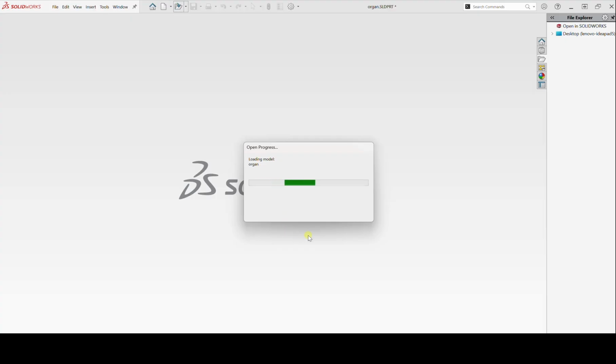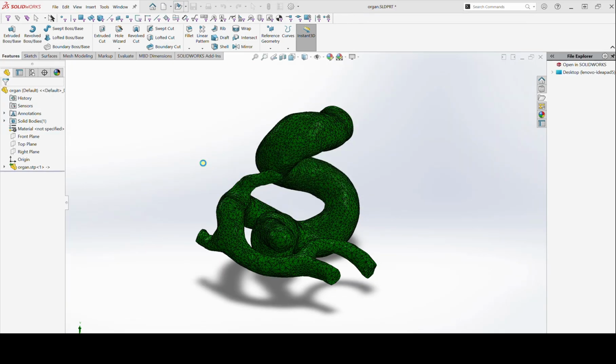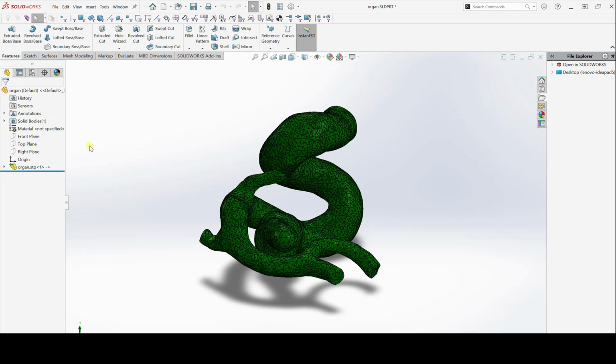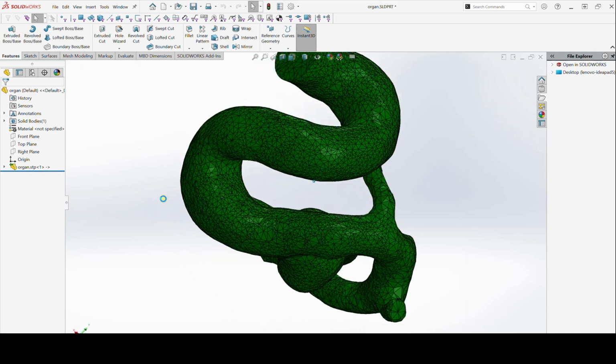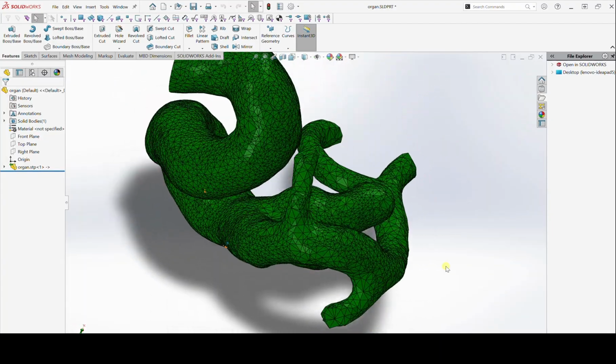It's just an import and an export. We can run a surface diagnostic on this, and we'll see that in general SolidWorks will say yeah, it's fine as is, and then we can do what we want with that data. This is a solid body, so we can drill holes through it. We can use other items on there as references.